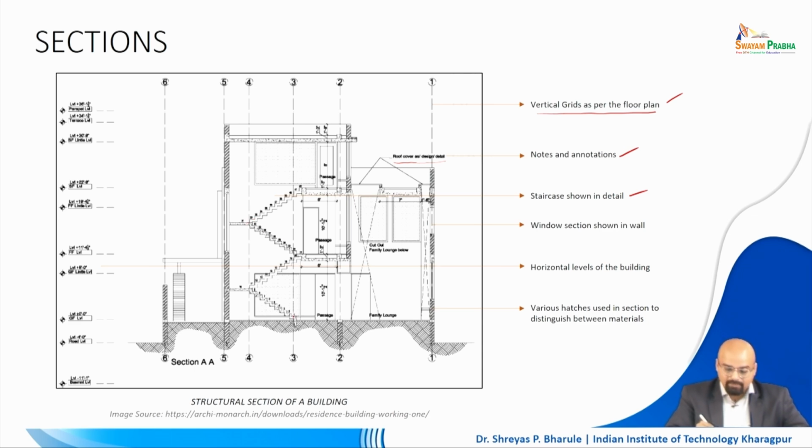All the steps starting from 1 here till the topmost step, the last step on top, including the mid landing, and all of this is to be detailed in a very clear, legible manner. Along with that, you also need to mention all the dimensions of all the clear heights which are there next to the staircase. Very important.